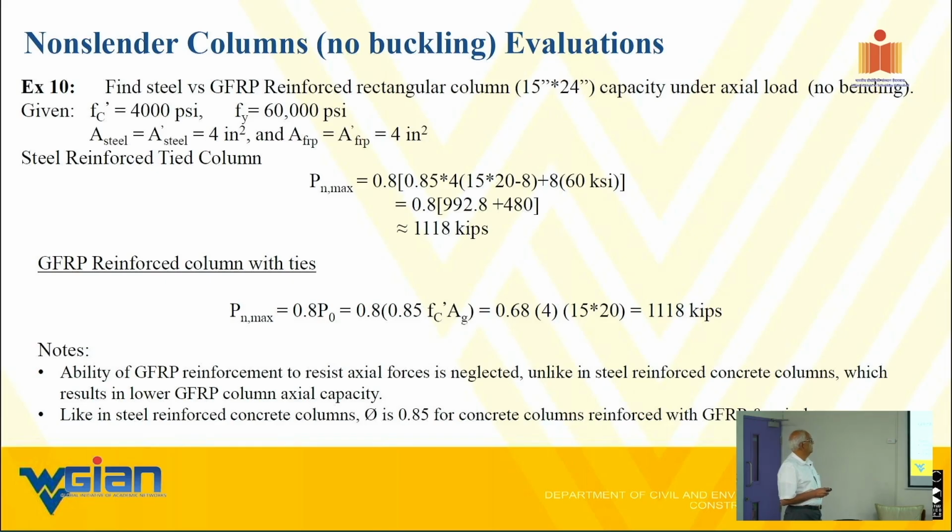So you can see, again, one can debate whether this factor is 0.8 or 0.85, but it's in that range. It's not 0.6, it's not 0.95, you know. And it's very difficult to get perfectly collinear forces acting from top to bottom in any construction. That is what that reduction is all about.